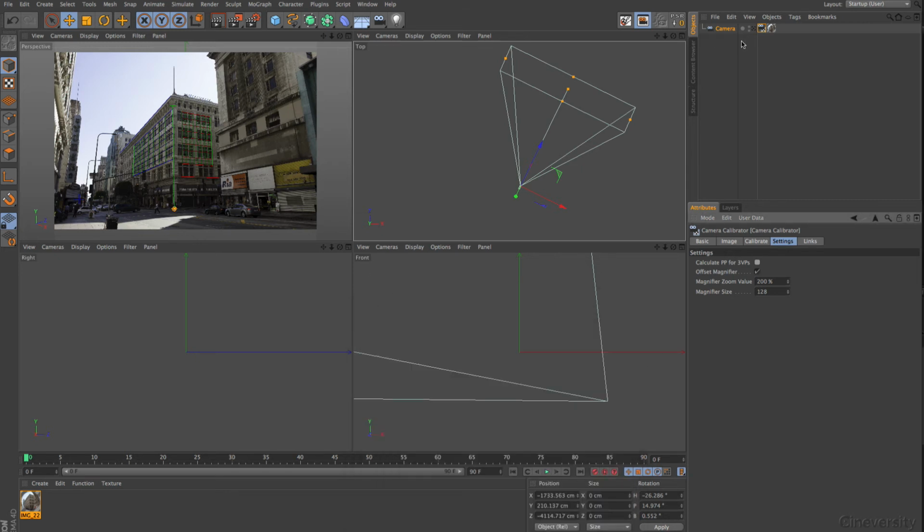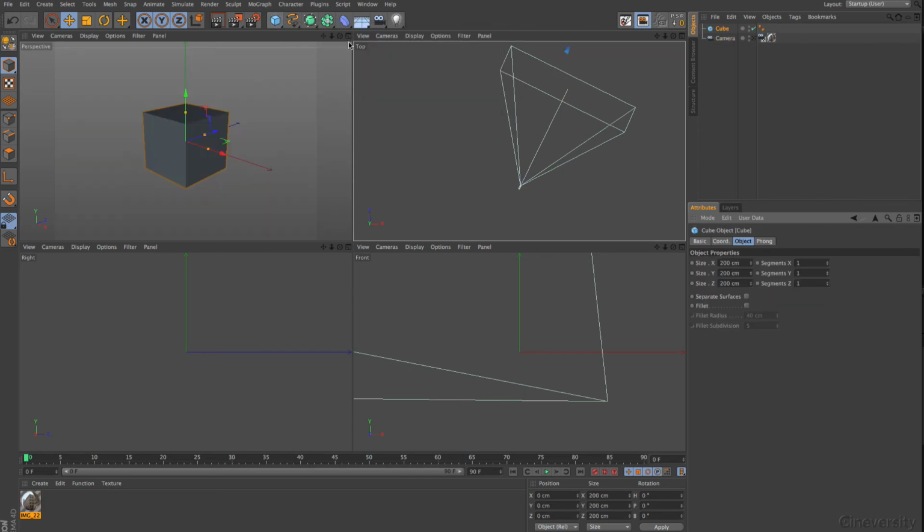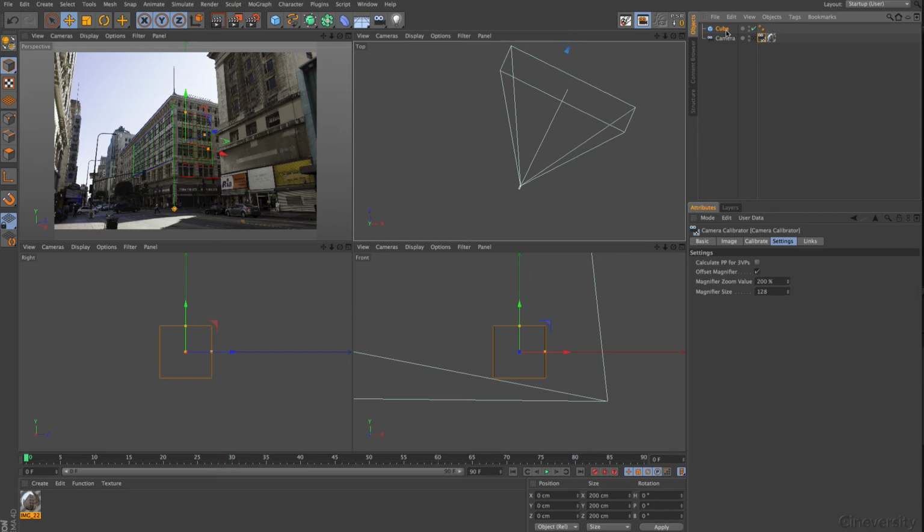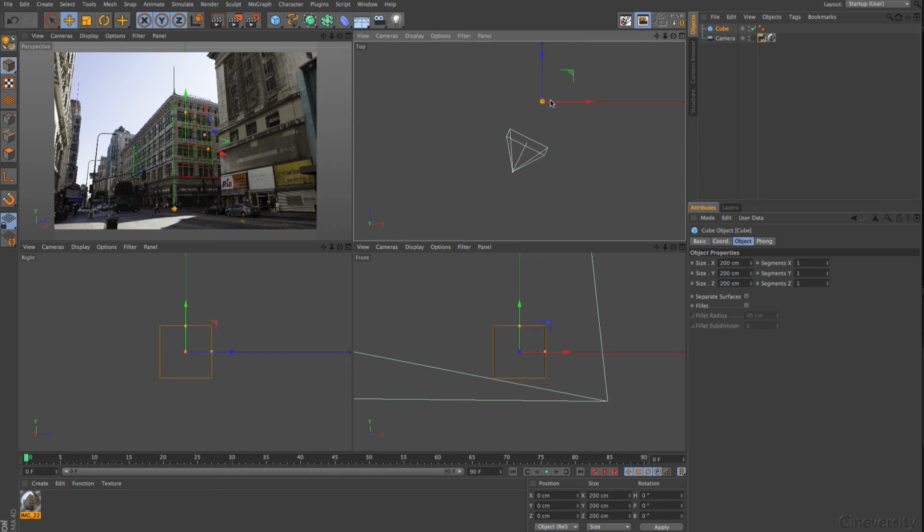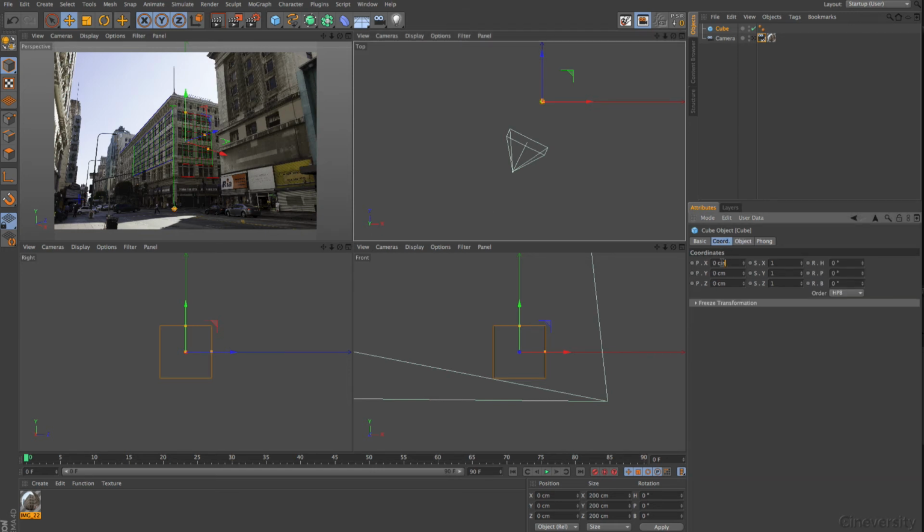It's very important. The next step is now that we create some geometry. I have done this with the geometry before, but I want to give you all the steps in case you haven't followed the whole series along. So my standard to start out is to take a cube, and that takes the selection away from this. So I take my cube, and I want to have this cube, of course, in a way that I can use it for this object here, which has the pin at 0, 0, 0. That means for me, I take my coordinates to 100, copy that, and Command V into it. So what I have done now is that I can see that this object has now its 0, 0 point exactly, whoops, at the world origin point.